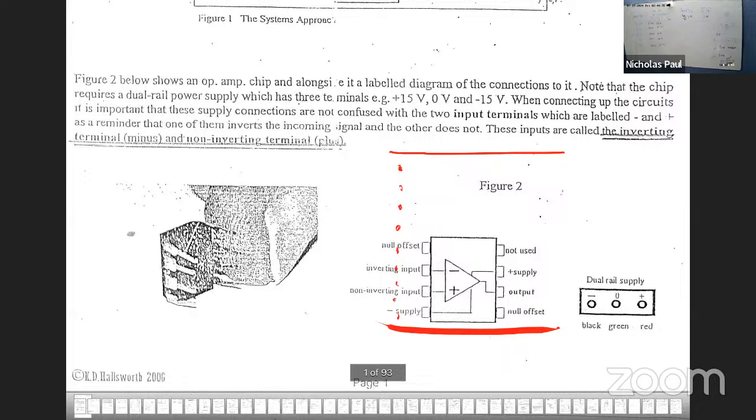For example, if here is 20 volts, here might be 0 volts. If you connect a wire at this point, let's pretend that's halfway, then it's 10 volts. If you connect it all the way to the top, that'll be 20 volts. Then sometimes you will see a reading like this, where they have opposite polarities. Here is 20 and the bottom is minus 20. So if I connect at minus 20 and at 10 volts, what will be the power being supplied? Minus 10.